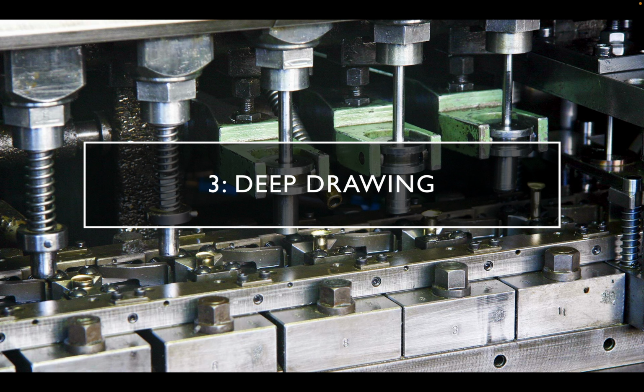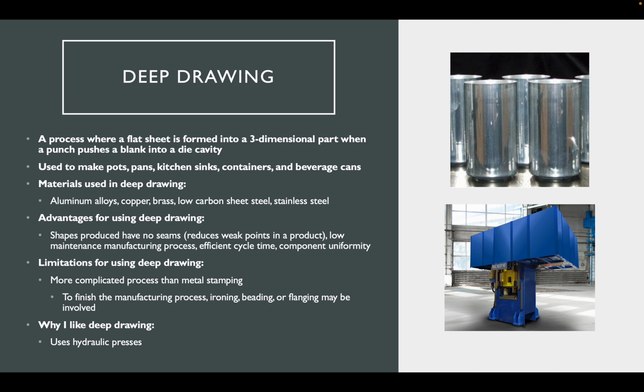The next manufacturing process I will be talking about is deep drawing. Deep drawing is a process where a flat sheet is formed into a three-dimensional part when a punch pushes a blank into a die cavity. This is used to make pots, pans, kitchen sinks, containers, and beverage cans. Common materials used in deep drawing include aluminum alloys, copper, brass, low-carbon sheet metal, and stainless steel.